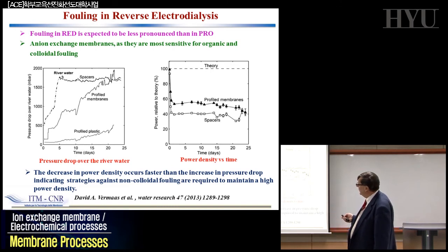But if we know in detail, we have to add here a kind of fouling related to the decreasing of the membrane permselectivity for specific interaction of some of the components of the solution with the membrane charge density. And people are not aware of this. It's very difficult to evaluate, and it depends on a lot of chemistry that still is under investigation.